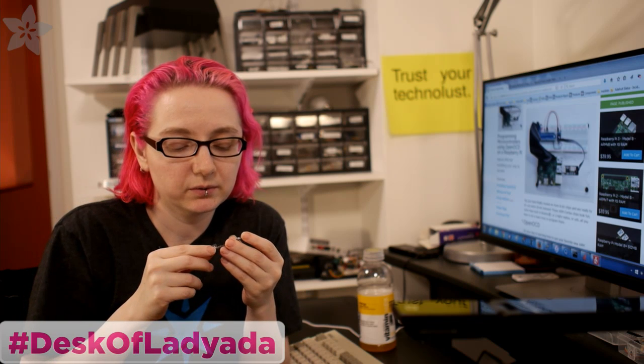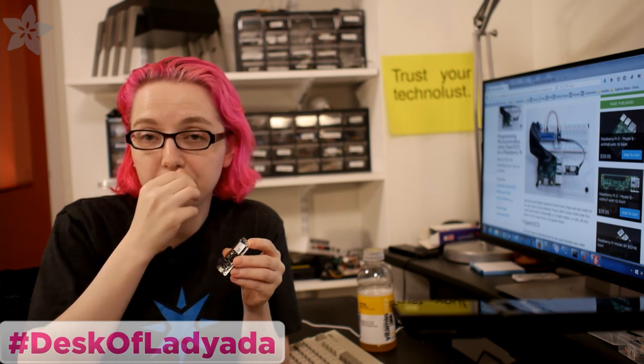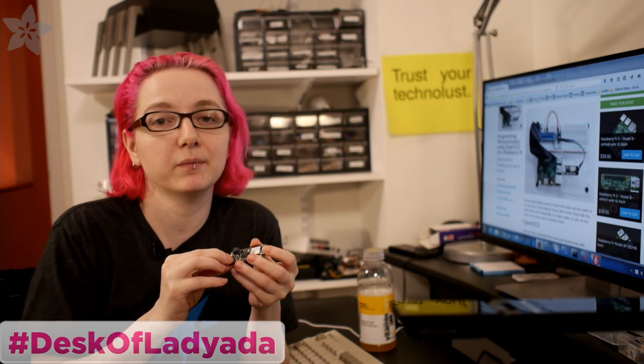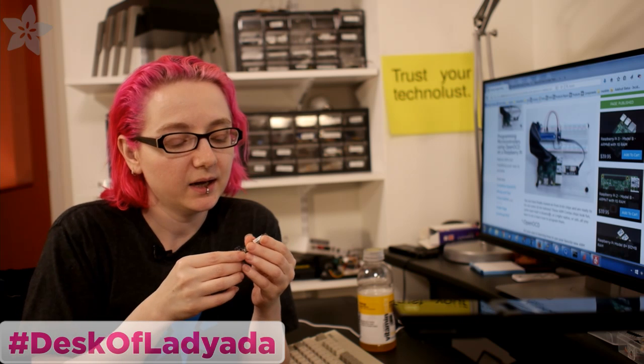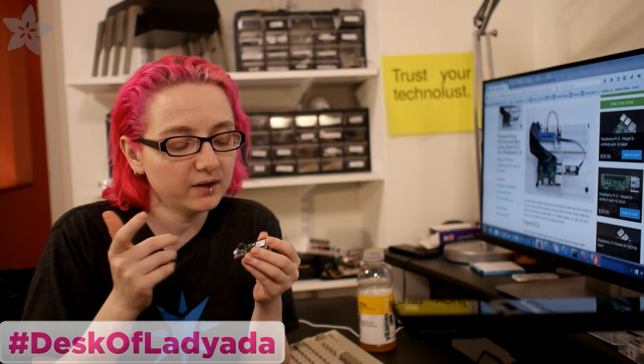If you have a bootloader, okay, you connect to the bootloader and use whatever bootloader tool. But if you're getting a raw chip from Atmel or DigiKey, they don't come with a bootloader, at least most of the time. I haven't seen any that do, although there are a couple of chips like the LPC1343 that came with a mass storage bootloader, which is super sweet. But Atmel didn't do that. I understand it's a little weird to have a mass storage bootloader burned into ROM. So instead you have to program the chip with a programmer.